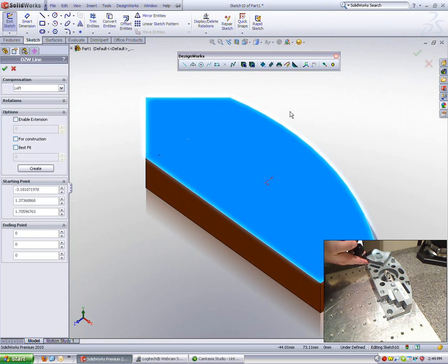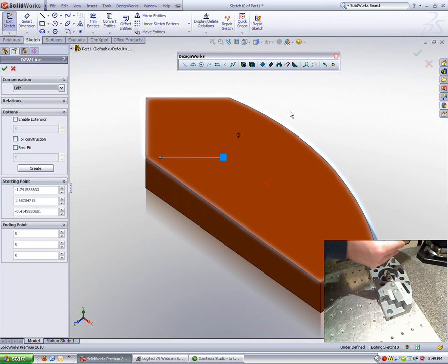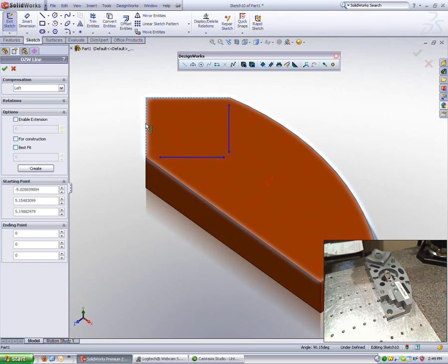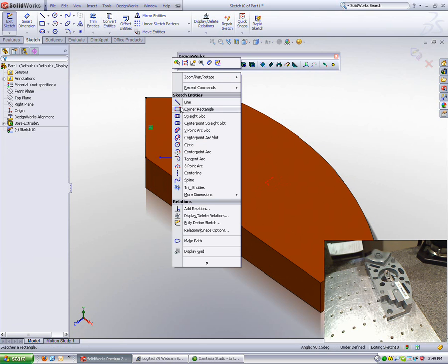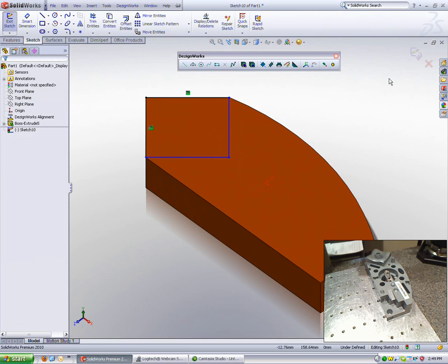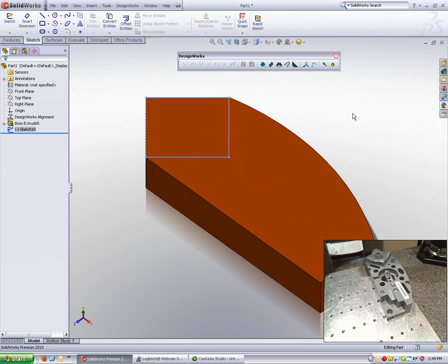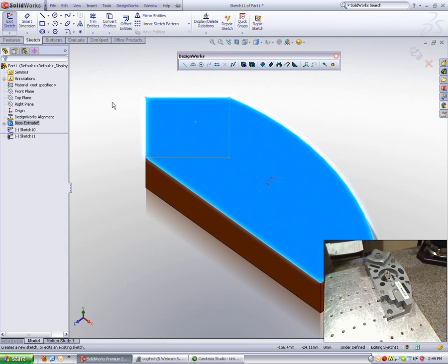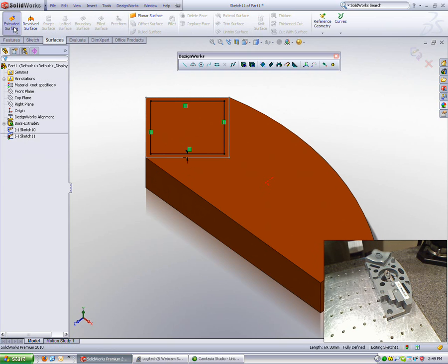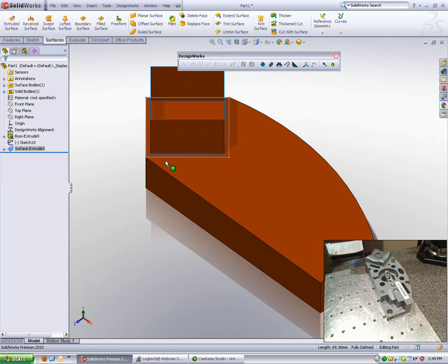Now we're going to do the complex surface along the top edge of this part. And that complex surface requires a few different sets of geometry to allow us to capture the information. So first, we're going to outline where that surface exists, again using standard lines and walking around that area with the probe. And then we'll use those lines to create some surfaces that we're going to scan through. Within Dezignworks, you're able to take surfaces or planes and scan through them to get cross sections. We're going to get some cross sections of the top complex surface there.